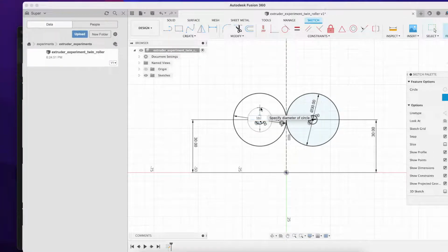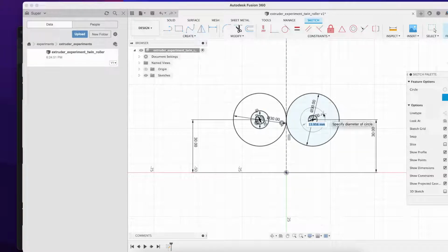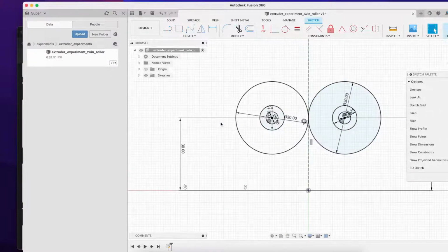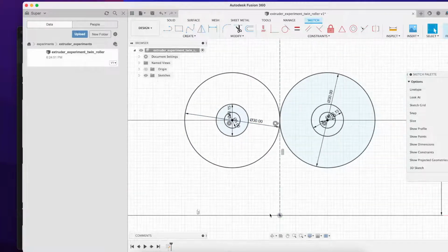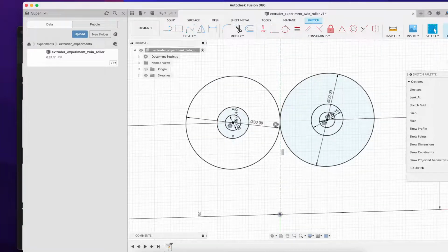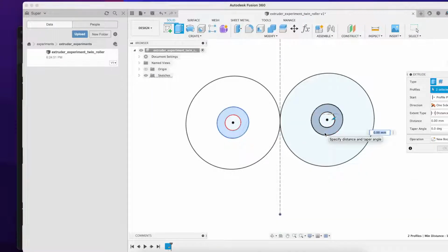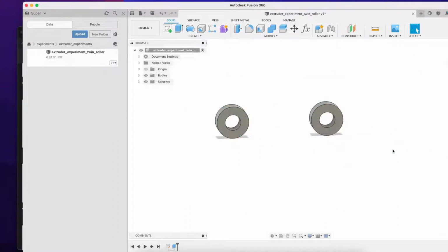On bearings I usually use 0.15mm as clearance, which seems to usually work. The thickness is 4mm, which is nice. So let's just extrude these. Yeah, that direction is fine. I like to make things look like bearings if they aren't, but I'll try not to do that now.